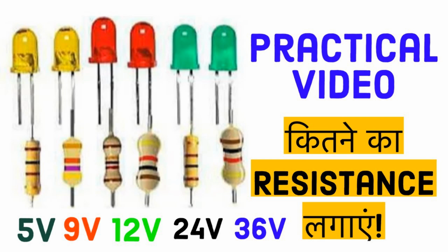Steps for matching. Calculate the reactance. Determine the required inductance, L, and capacitance, C values to create a matching network. Design the network. Configure the components in either a series or parallel arrangement to achieve the desired impedance transformation. Test the system. Measure the VSWR, voltage standing wave ratio, or reflection coefficient to confirm that the impedance is matched and that minimal signal reflection occurs.